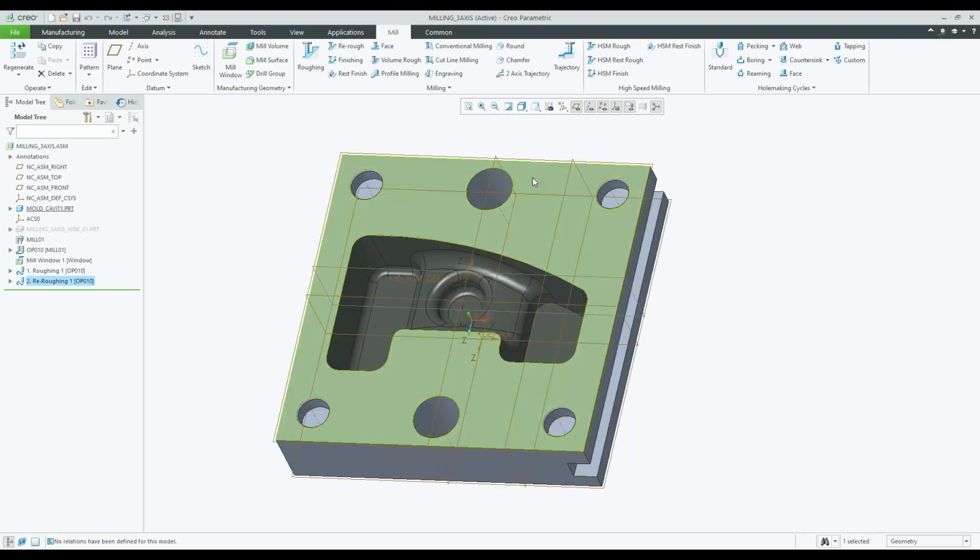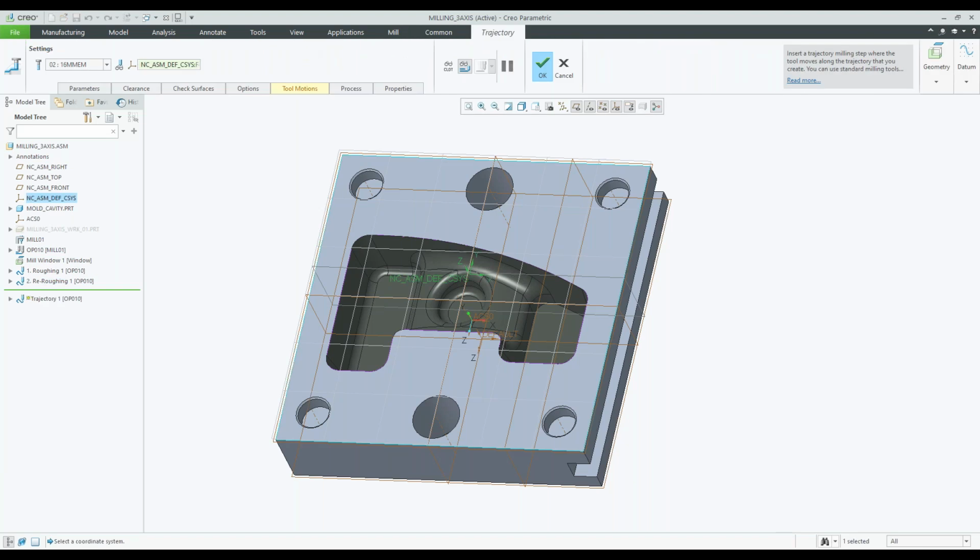So I want to create a trajectory milling. So this is really one of the sequences I use the most when I work with 3-axis machines. Okay, so I'm going to select my parameters. I'll just have a quick glance over that. Okay, so I think that's fine for default settings. And then I need to go and specify a curve cut.